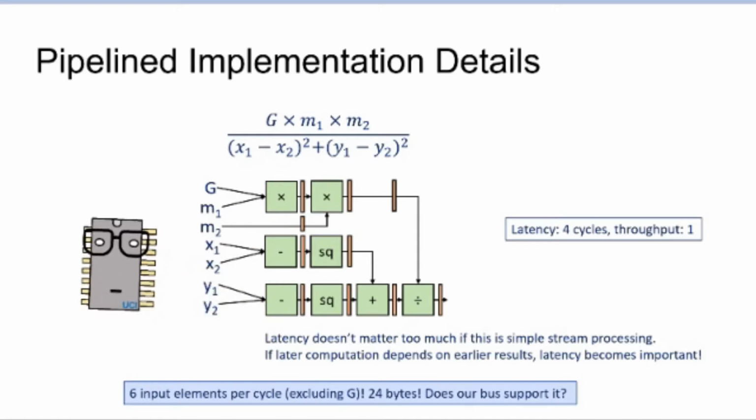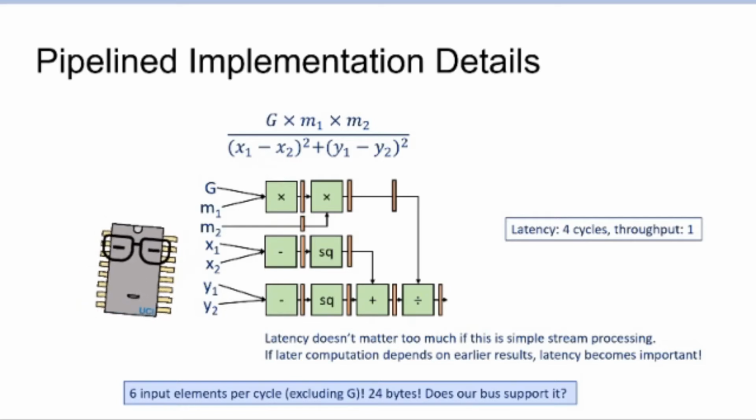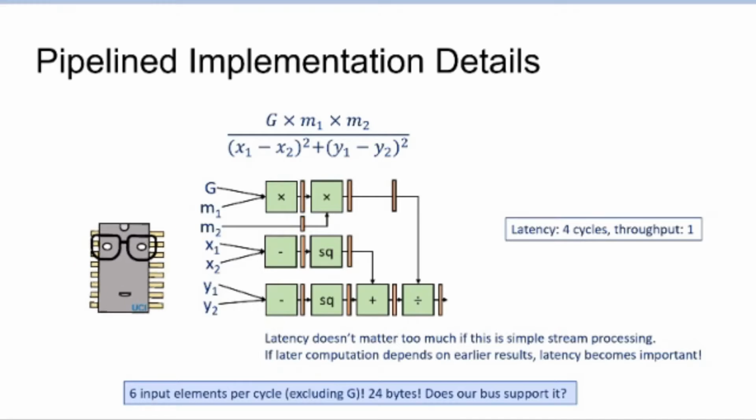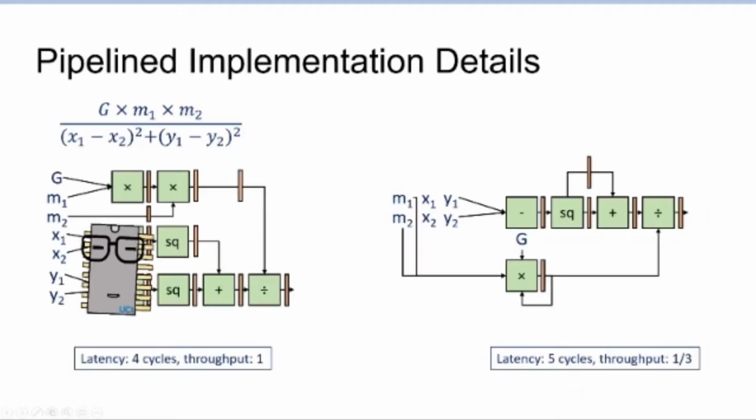So some of these devices, some of these arithmetic operators, if the data bus is too narrow, if the incoming data throughput is too small, too slow, then some of these arithmetic operators will be sitting there idle, not doing anything important, just taking up chip space. And that might be okay if chip space isn't a critical factor of the design that you're doing right now. So there's a lot of freedom when you do FPGA design. But if it is, then you might want to do something different again. Something like this, perhaps.